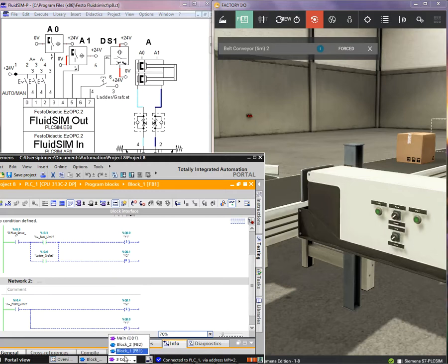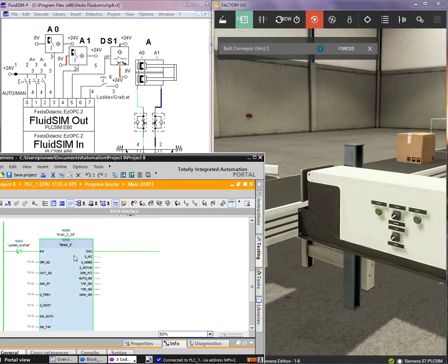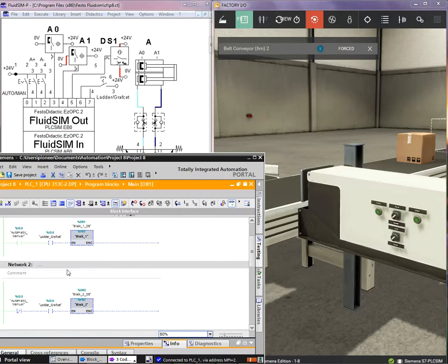Let's see. I should go to the operation block, or OB1. I use 3 blocks: FB1, FB2 and FB3. I wrote the graph set language in FB3 and the ladder language in FB1 and FB2. I divided the ladder language into 2 sections. FB1 works for the automatic mode, and FB2 works as the manual mode.